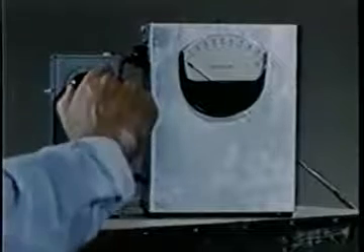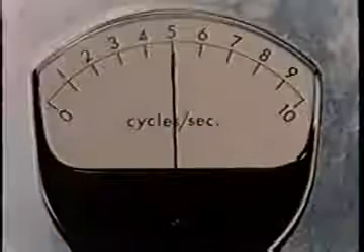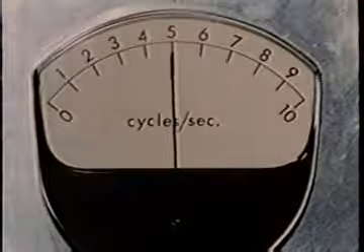In order to find the frequency response of amplification, we put in sinusoidal disturbances which we can control. We start the wave maker oscillating at 5 cycles per second, at 0 airspeed. The waves damp as they travel away from the wave maker. With the tunnel running but below critical airspeed, we don't notice much change in wave damping. As we increase the airspeed and pass critical speed, we see the waves grow.